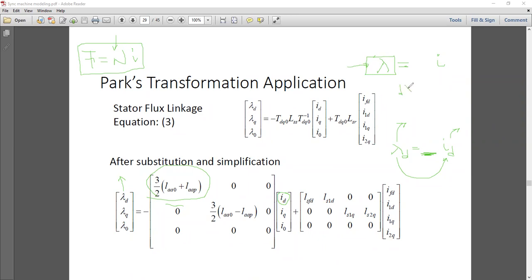What is d lambda over dt? Can anyone remember? Can you recall now? Rate of change of flux linkage can be represented by L di over dt. So if you cancel out the d by dt terms, what is left? Lambda equals Li. So this blank space should be filled up with some sort of inductance, right?